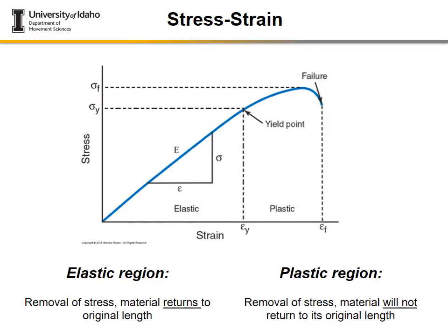So there are a number of regions of the stress strain load deformation curve, and we'll talk about first just the 2 major regions that we want to discuss, and that is going to be the elastic region here, this first part, and also the plastic region. These are the 2 major regions, and the elastic region is the portion that represents the elasticity of the material. And elasticity means the ability to recoil and rebound, right? So when the stress strain relationship is within this region, the material will return back to its original length and form following the removal of that stressor load.